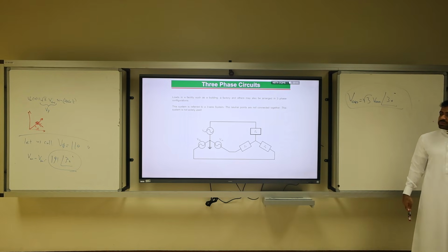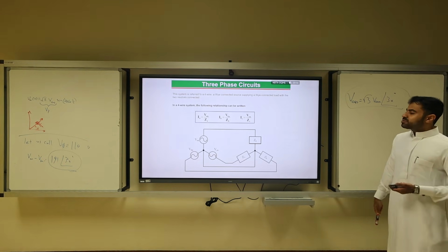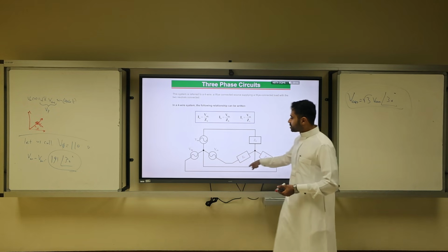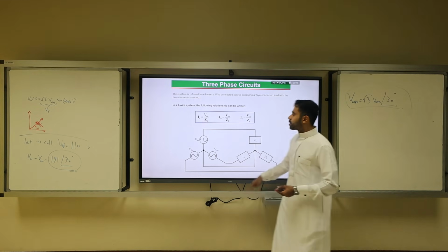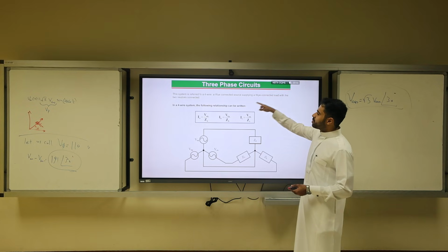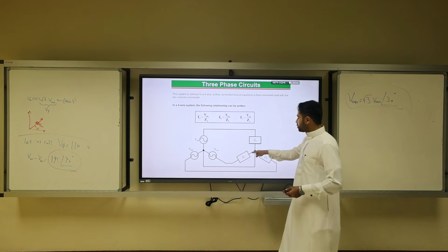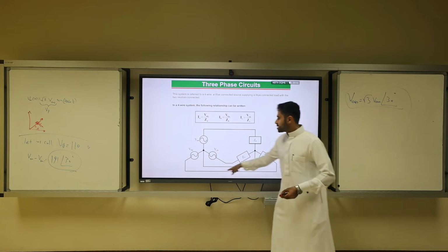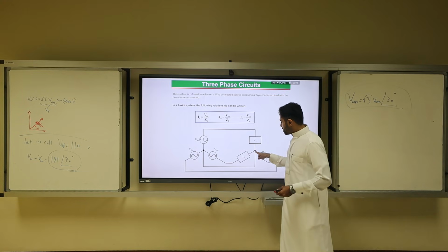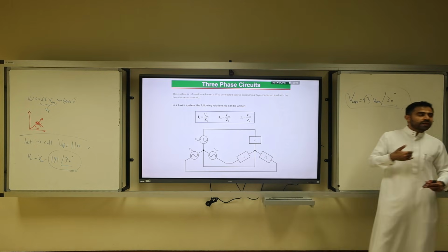It's very important. Now what is happening here is sometimes we add a 4th wire where we connect the 2 neutrals together. We connect the source and the supplied Y connected load with the 2 neutrals connected. This is the first connection of the neutral, this is the second connection. This is neutral 1, this is neutral 2, we connect them. This is usually feasible if you don't have a very long distance.